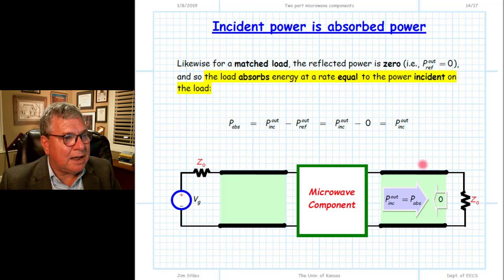The reason we do this is now we can talk about the incident power flowing along the line, in this case incident on the load here at the end, and the reflected power from that load. Of course, we know since this load is numerically equal to Z0, it's a special case, and the reflected power in this case is equal to 0.